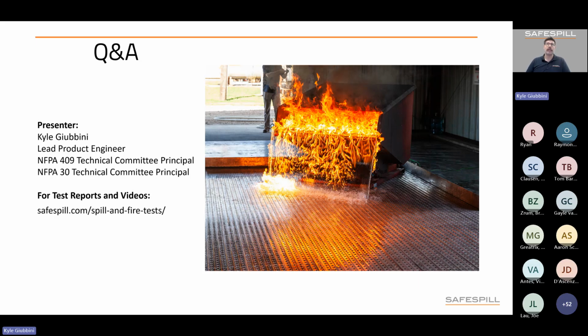applications. If it's a retrofit, it's important to locate trenches, and we may need to modify the routing of that radiant slab heating to go underneath the trenches that are installed. If we don't need to modify trenches in any way, or if it's a new build facility, it's perfectly compatible, and that radiant slab heating is routed in the same way that it would be, just going around the trenches. So again, with radiant slab heating, the only issue is that if we're excavating and we would be cutting through the tubing, we need to modify the routing to accommodate it.